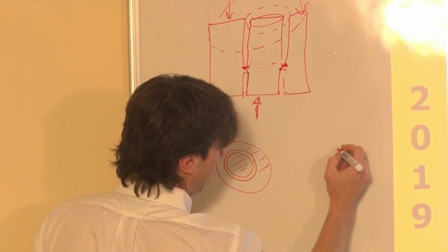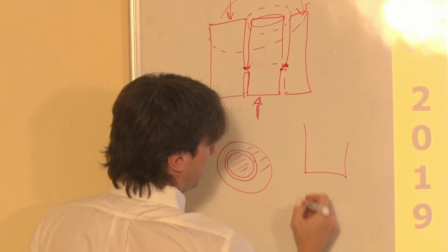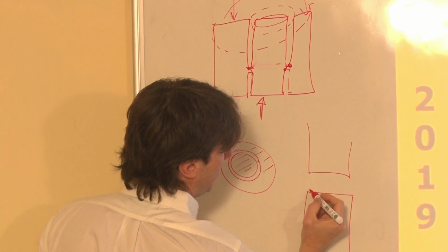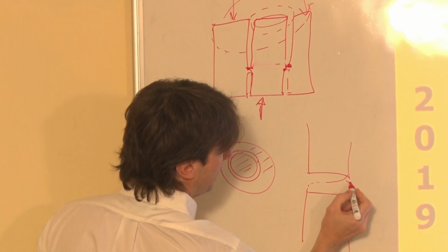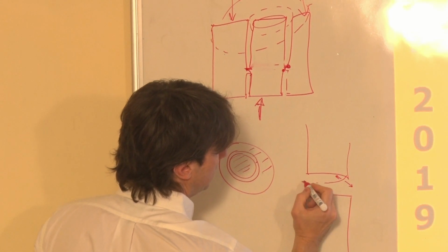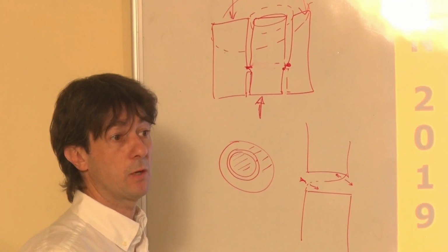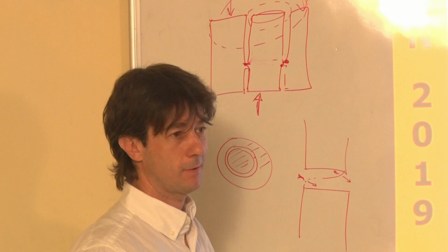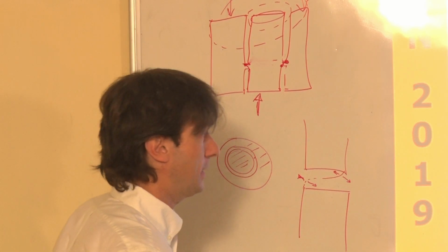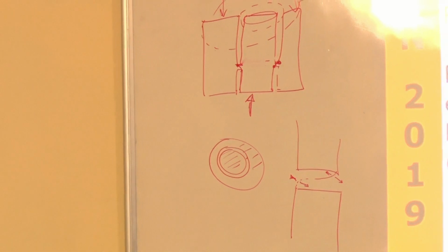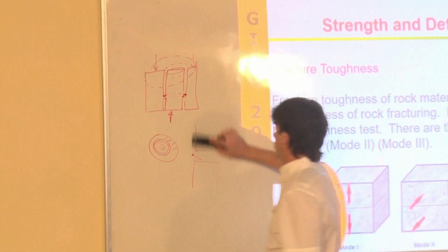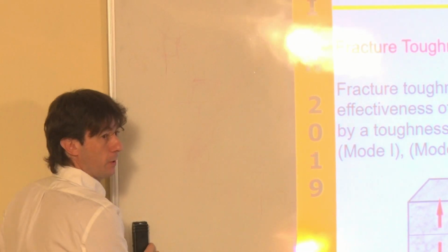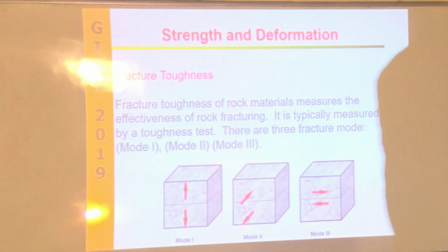So if we do that, you push. Basically what is happening is that you have a tensile, all this is open. So it's basically a tensile stress that will initiate the fracture, and then the stress will rotate and will jump. It's always like that. And you can model it, it's very simple. Despite that, they claim, or they accept, that this is mode 2. To have a successful test, you need probably 15 of those tests, and you might be able to claim one successful. I personally don't trust them.